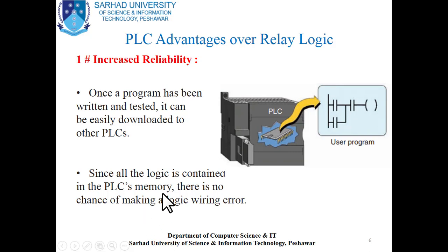Since all logic is contained in the PLC's memory, there is no chance of making a logic wiring error. If we connect our laptop to this PLC, from the laptop we can program the PLC, and in the laptop we can use a ladder logic program, in which we can design specific control by using Boolean logic.